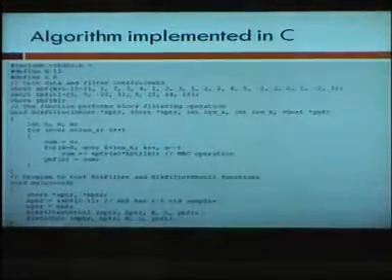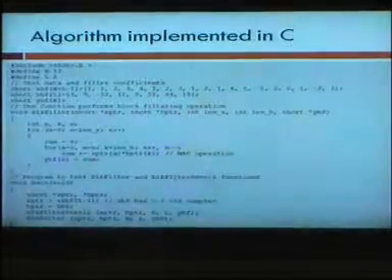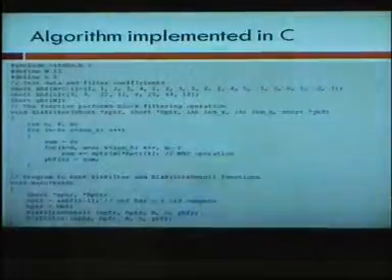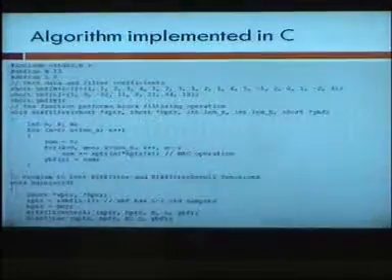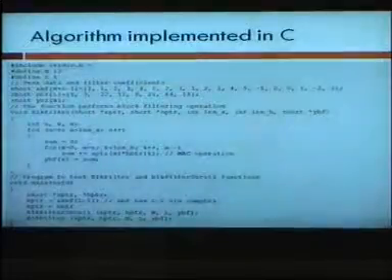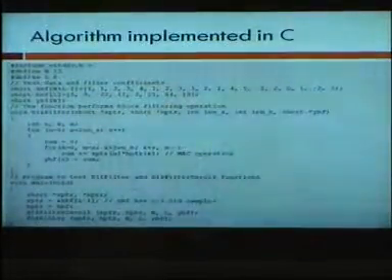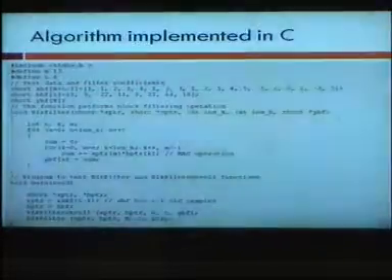As you can see, I have taken more values of x just to show that first x of n is this, then x of n is this. It's a dynamic buffer which is changing all the time, but usually you don't keep so many values, you just keep the number which is actually required, which is 10. So 10 samples are more than enough to keep in this buffer, but you have to update this buffer every time you compute an output value.